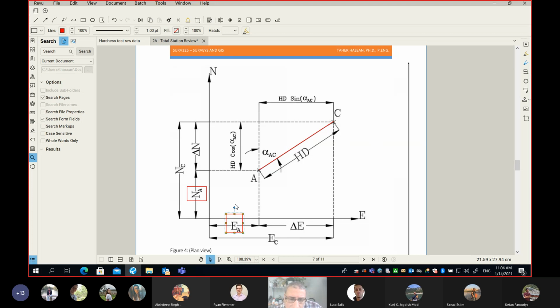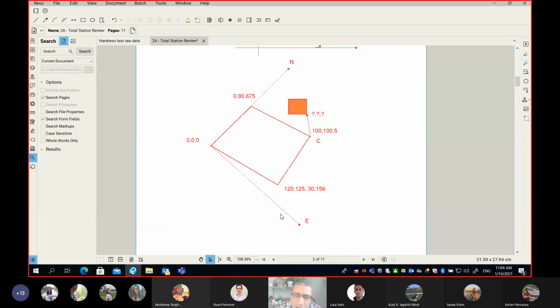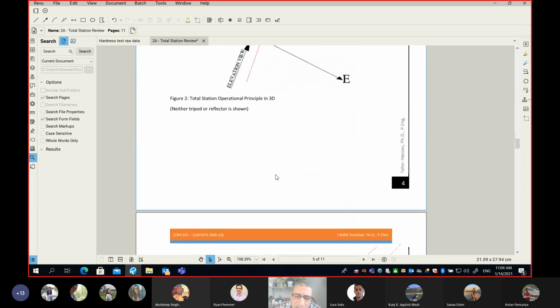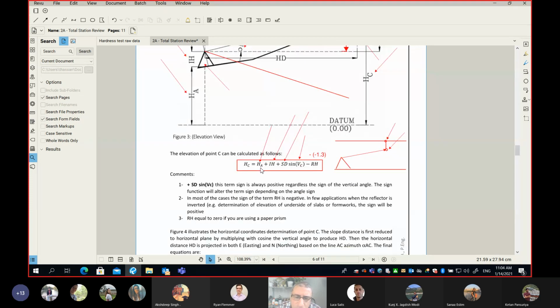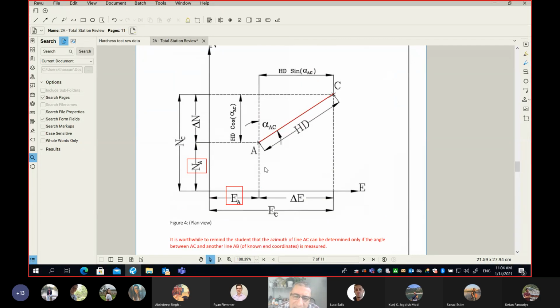At this point of time, do we have those numbers? Yes or no? Yes, we should. Yes, thank you so much. You have them after you adjust your traverse. If you remember, I'll take you back to remind everyone that once you adjust your traverse, for every traverse point we do have three-dimensional coordinates. And that's why anytime you see point A, you know that the H of point A and the easting and the northing, the three of them, are known values.